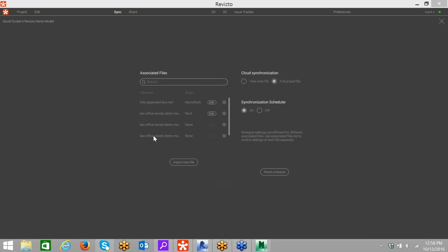What about working with design options? So design options coming out of Revit, we do not support that currently. You can turn on one of those design options and re-export as a separate project. I know that's not the ideal workflow. It'd be nice to be able to filter those out in Revizto. It's something we're aware of, and I think it's something we'll address in the future. But currently today we cannot bring in multiple design options.